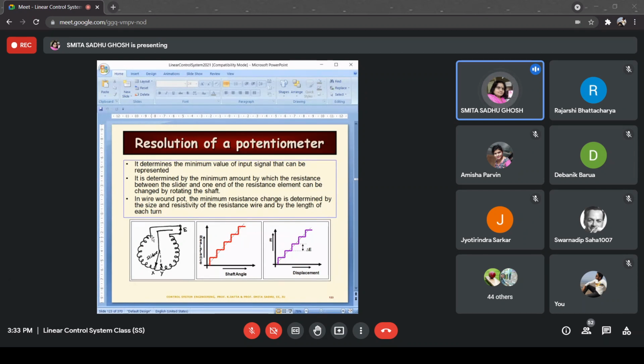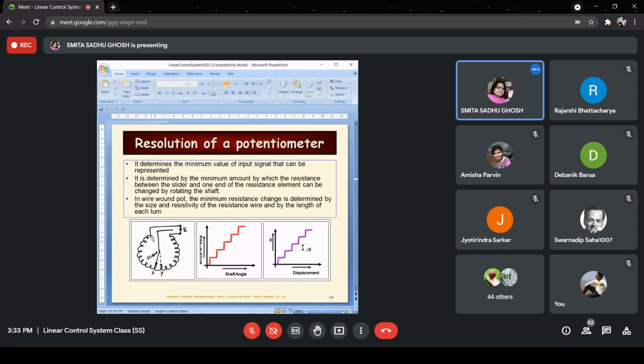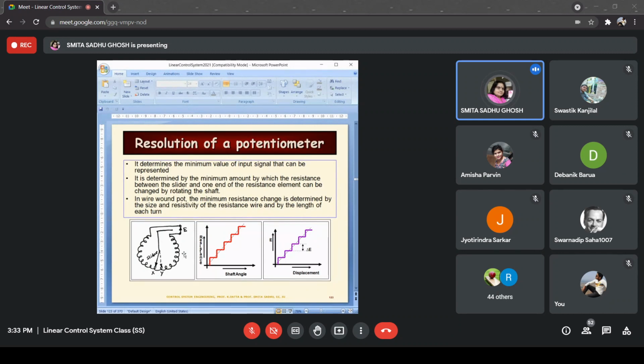This is a resistive element, mind you. So what will happen if I use a thinner wire? It can't carry a larger amount of current, because it has a greater probability of getting burned. Yes, there will be a larger amount of heating. Thinner wire means your resistance is going to increase, and as a result heating will take place, and as you said, ultimately it may result in burning.